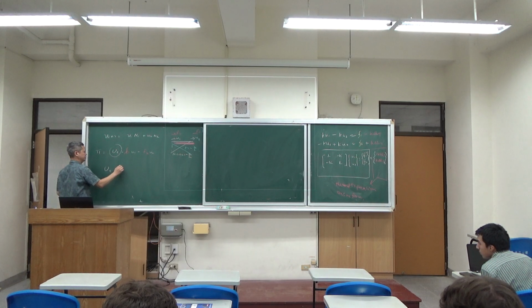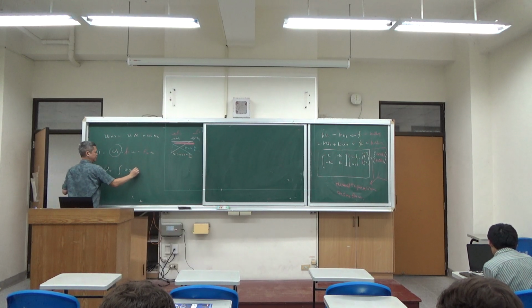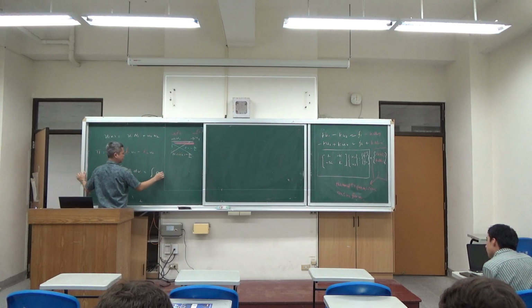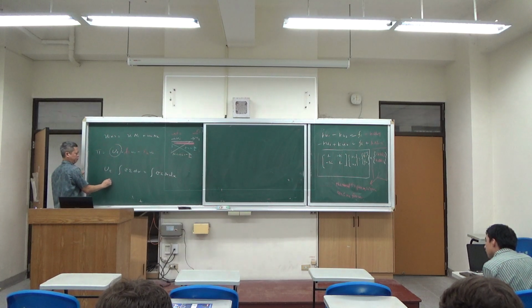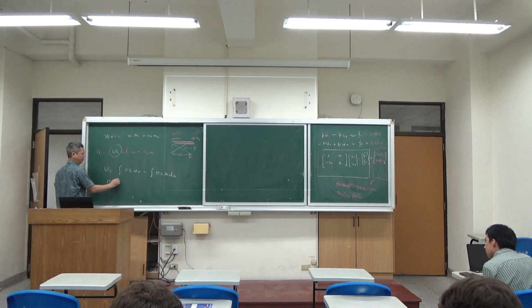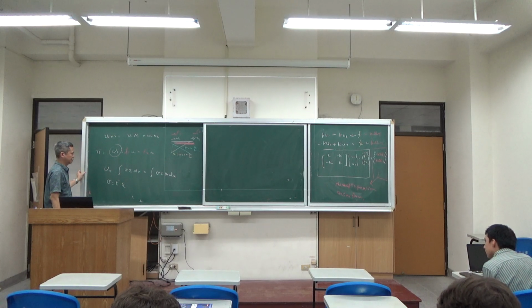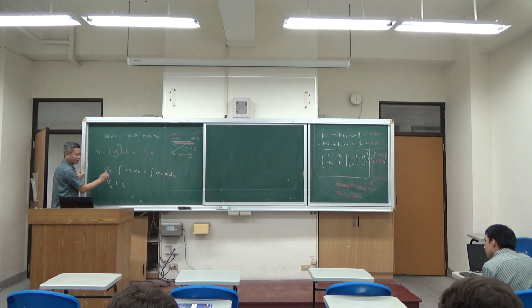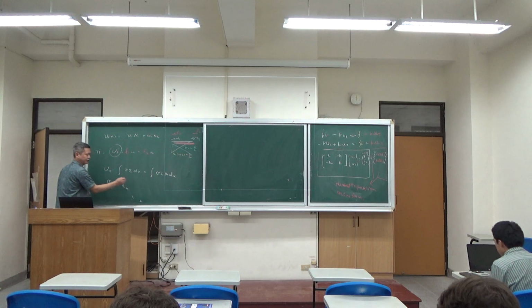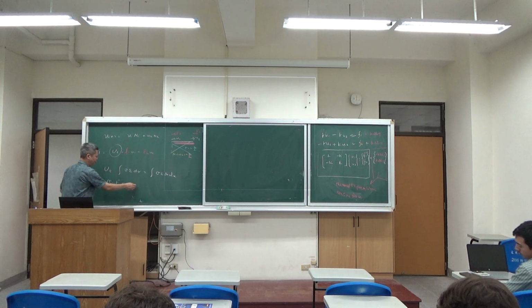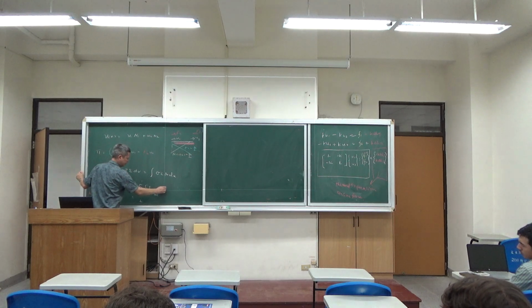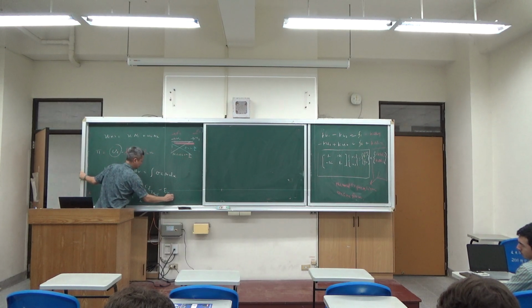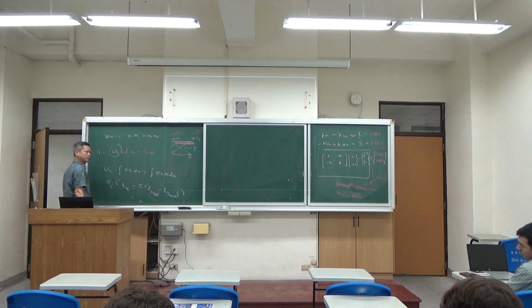Previously, the potential energy is defined with the stress, strain, and area. This mechanical stress is defined as Young's modulus times the strain. But in our calculation now, this mechanical strain is the total strain minus the thermal strain.